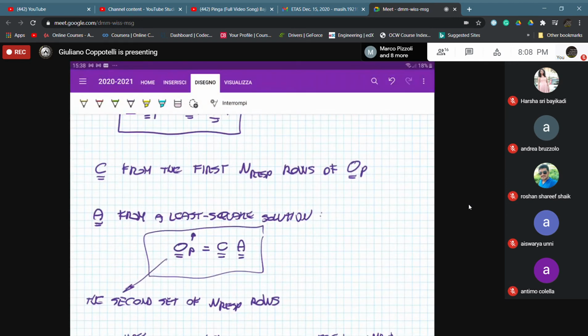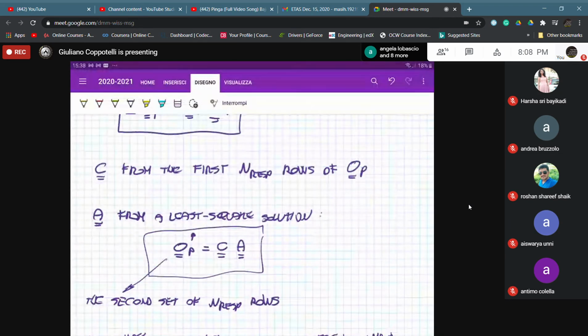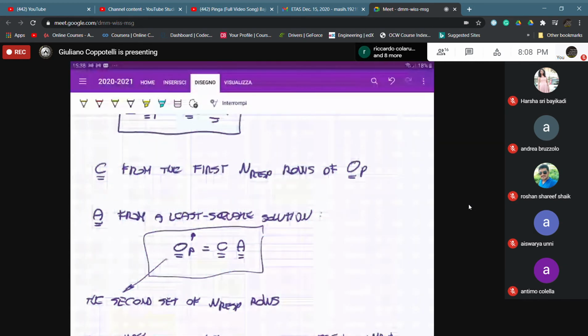Okay, then from the knowledge of A, you have the eigenvectors, then you have the eigenvalues, and then you put them in the stabilization diagram, and then increase your P value and do that again until you find that those natural frequencies and damping ratios are not changing at all by increasing the order, by increasing P, and therefore you are done.